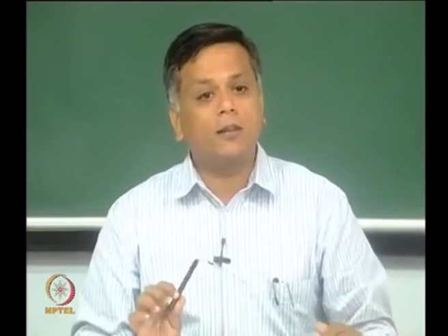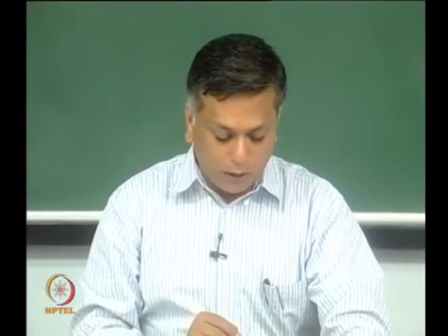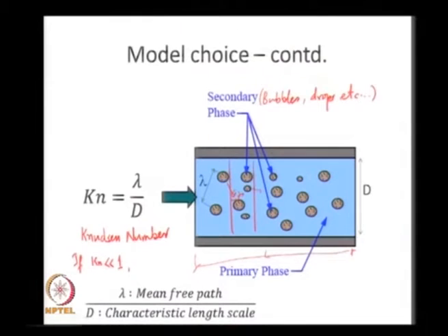Other fellow particles have a great influence on it. That is a diffusional process. Okay. That means, I am ready to make the assumption that I can postulate a continuum to replace these bubbles. So, if I estimate the Knudsen number, and if this Knudsen number is very small, I can postulate a bubble continuum.